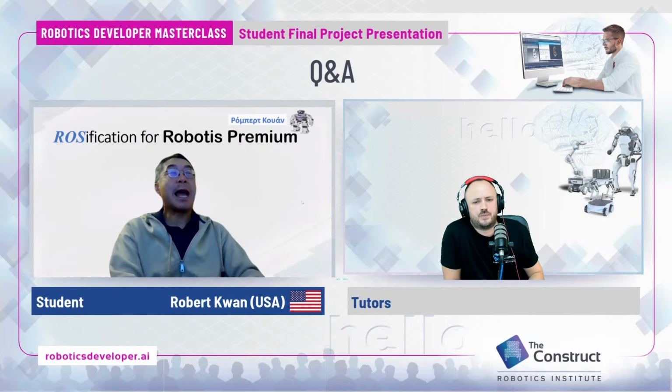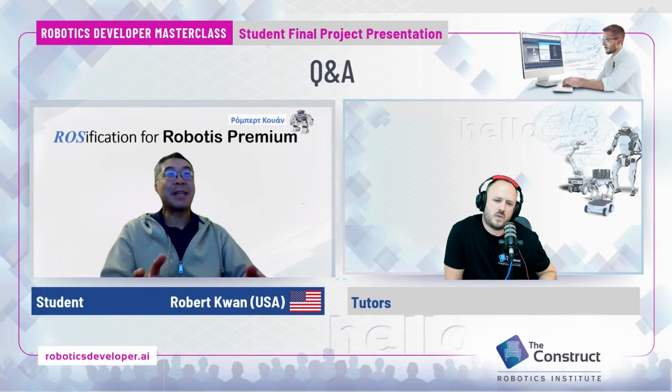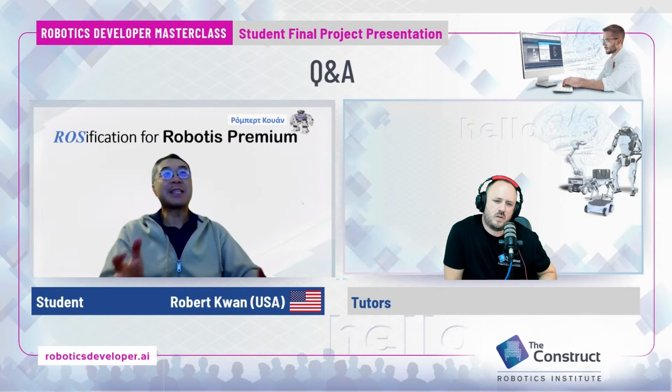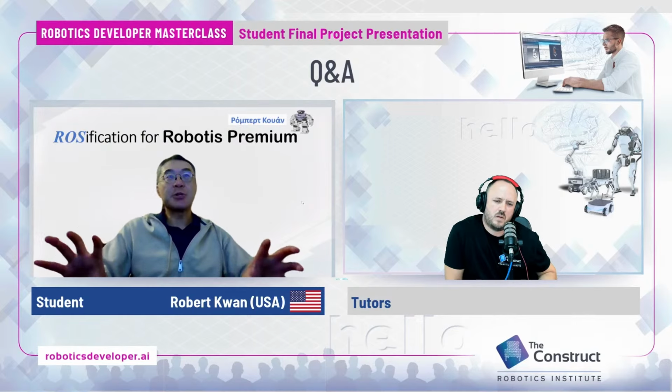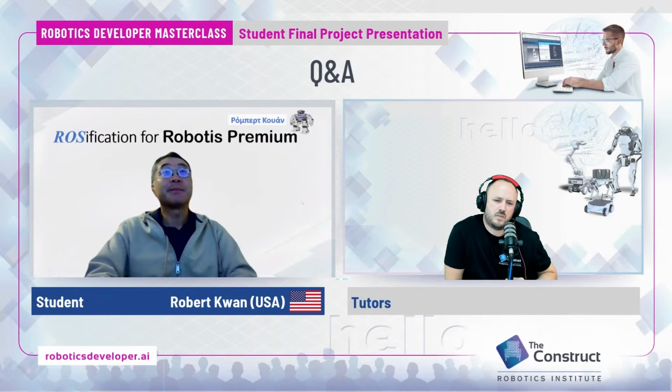I looked into some online resources. They suggest you should buy two U2D2 modules so that you split the motor control into two different sets, so each one only has to control 9 motors. Then that would make it faster and easier. But that would add more work from my side, because I may have to figure out how to coordinate the two different sets of controls.